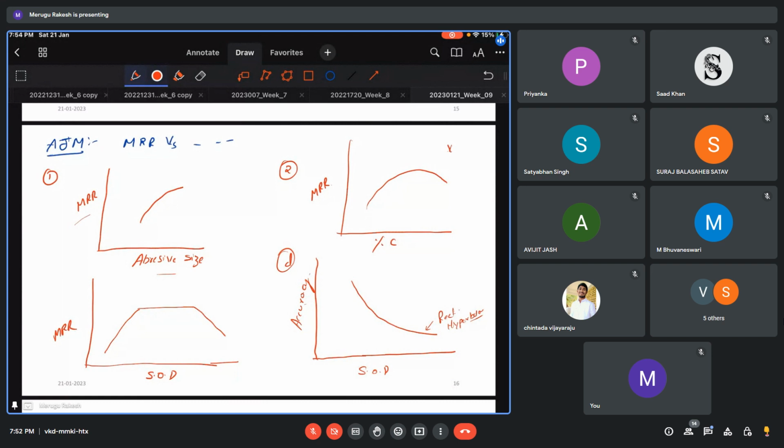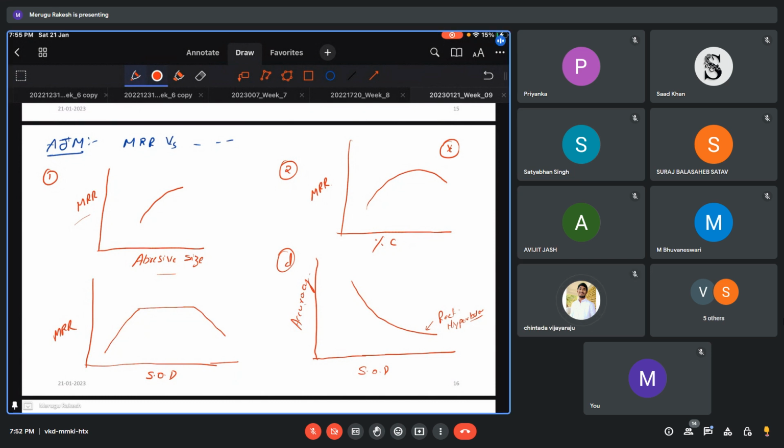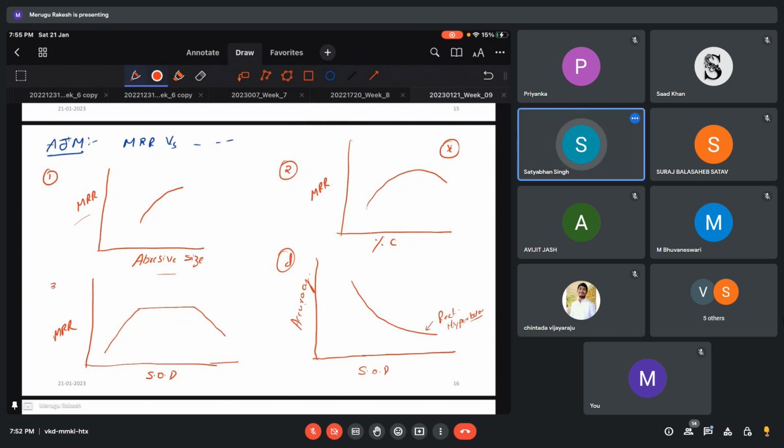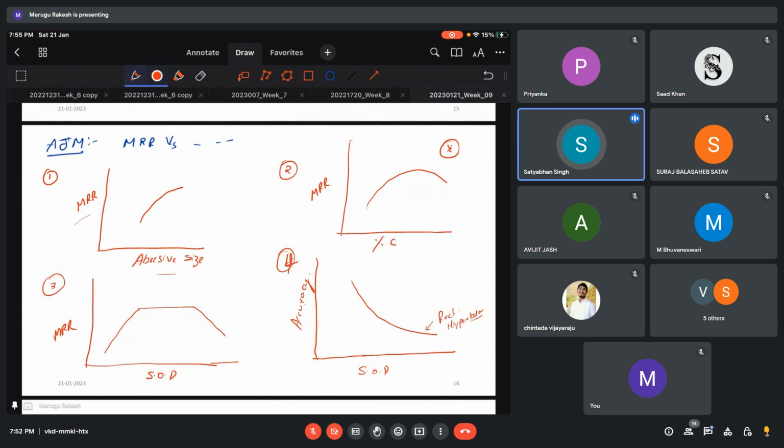So can you guess what the reason is here? Grain to grain collision, less momentum. Yes, less momentum transfer in this case with respect to percentage of concentration. So what happens in case of standoff distance? The particles are not able to attain the specific momentum required for brittle failure. Okay, that is why it reduces.